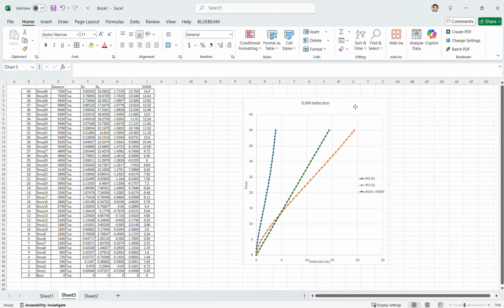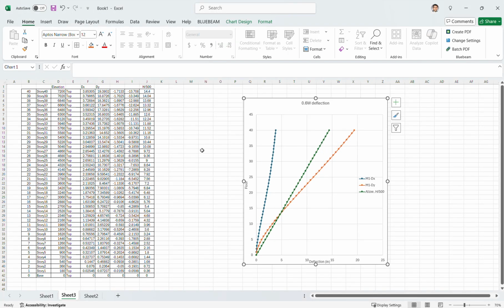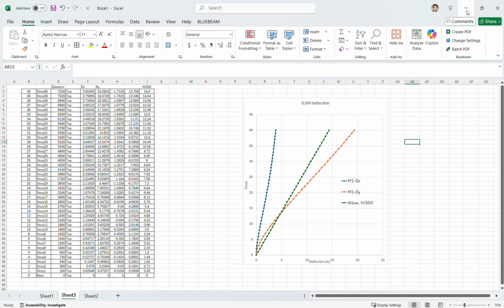All right, so next step, because this first model I used a 24-inch wall with concrete strength 9 all the way up, but still our deflection, especially Y, exceeds our criteria, H over 500. So basically we need more stiffness. This is basically homework 1 and exercise, but we need to find the right stiffness.